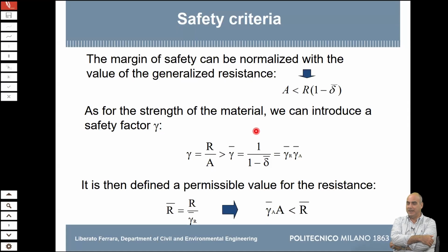Okay, that is in India. In Italy, it's 3.5 kilonewton per meter square. So you already see. And have you an idea of apartment buildings in Europe are designed for 2 kilonewton per meter square? Okay. Have you an idea of what does 2 kilonewton per meter square mean? So can you figure out physically, what does 2 kilonewton per meter square mean? Don't tell me 200 kilos because it's the same.